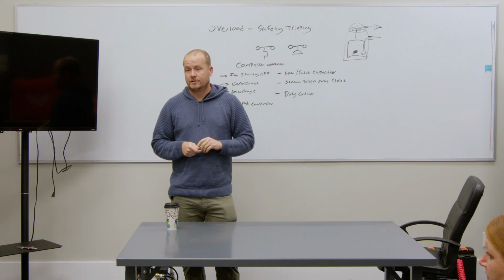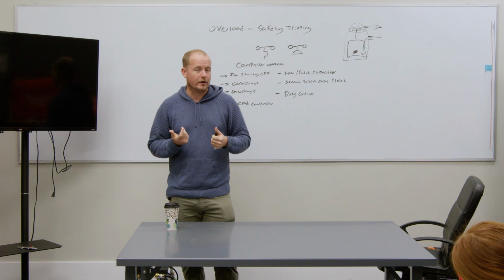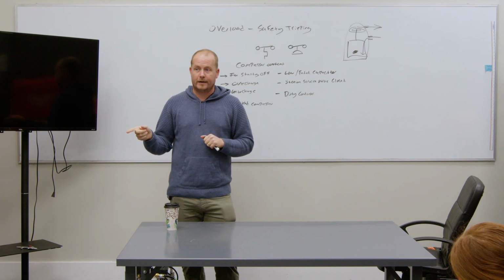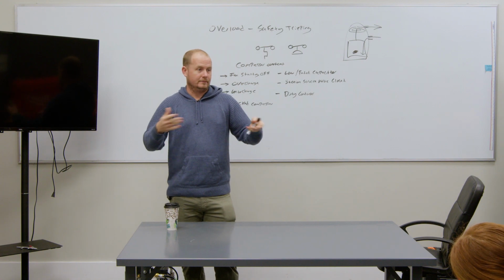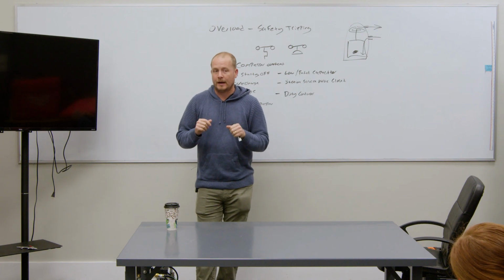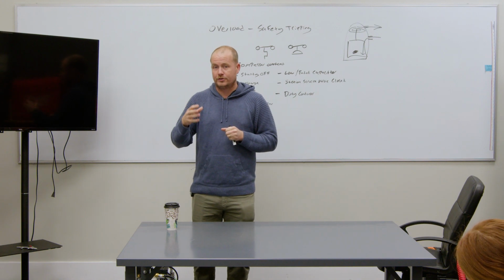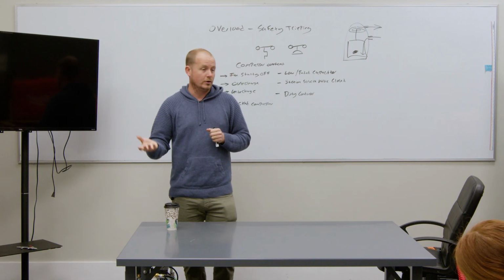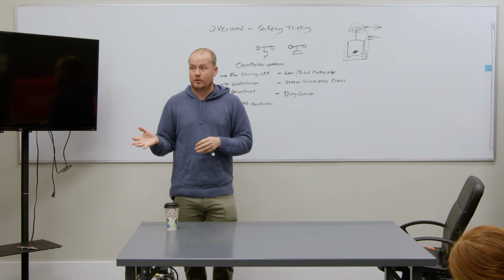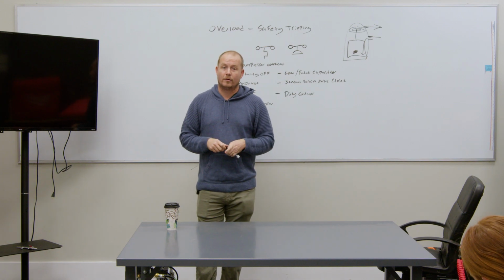Compressor cooler. So the CoolPresser, that little magnet with the hose, that's one thing you can do. You can run a hose on it. Just keep in mind that when you run a hose on it, make sure that, first off, power's off, and that you're not running a hose anywhere that water shouldn't go, so be careful with that. But also keep in mind that sometimes it takes a long time, and so I don't want you just condemning a compressor because a hose was run on it for an hour and it still didn't reset. In a case like that, we can tell the customer, we're going to quote you a compressor, but this could reset, leave it overnight, try it again in the morning.